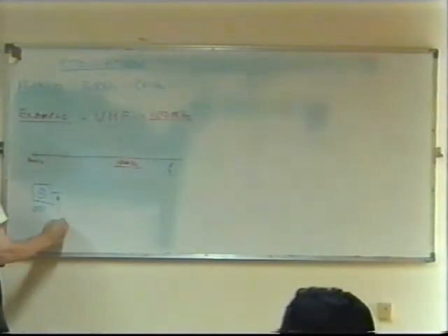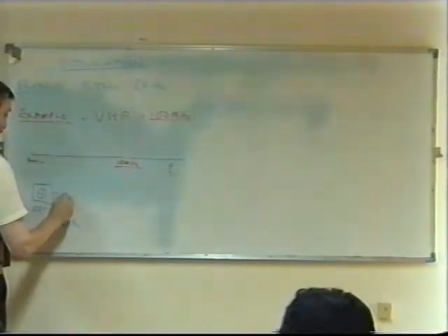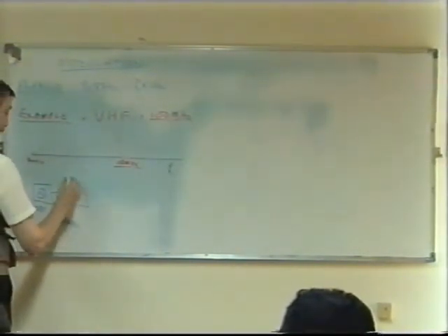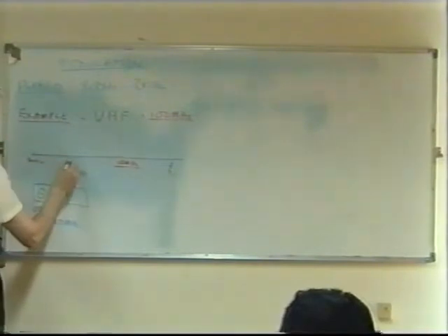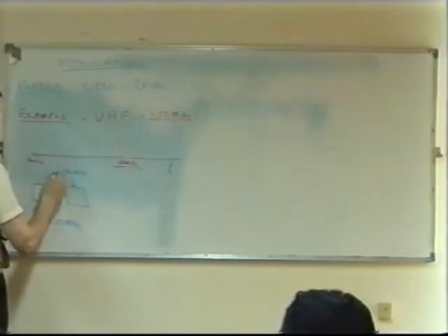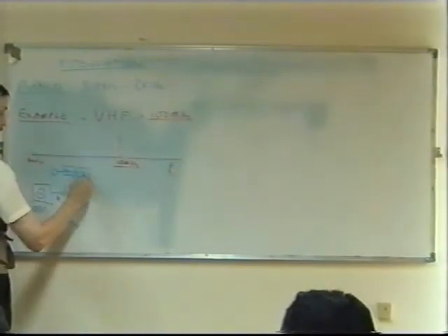And here we have 100 megahertz output. Now, what we do then, we put it through another stage where we mix the audio, that is these sets of frequencies here, which could come from a microphone and amplifier. So we would have some type of microphone here, which goes through some audio circuit, basically an amplifier.